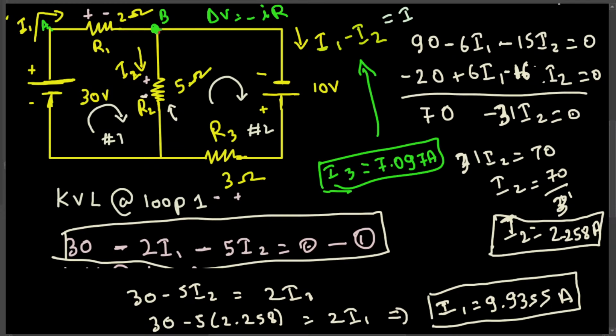By doing that, you can calculate the voltage here, and the exact same voltage is going to be here as well, because we don't have any voltage drop or resistor or anything. So the voltage is going to be exactly the same here, and the voltage at this point is going to be additional, with plus 10. Let's say you're getting voltage X here, the same voltage is going to be here, and the voltage here is going to be X plus 10 because of this voltage source right here, the battery. Okay, that's all you have to know.